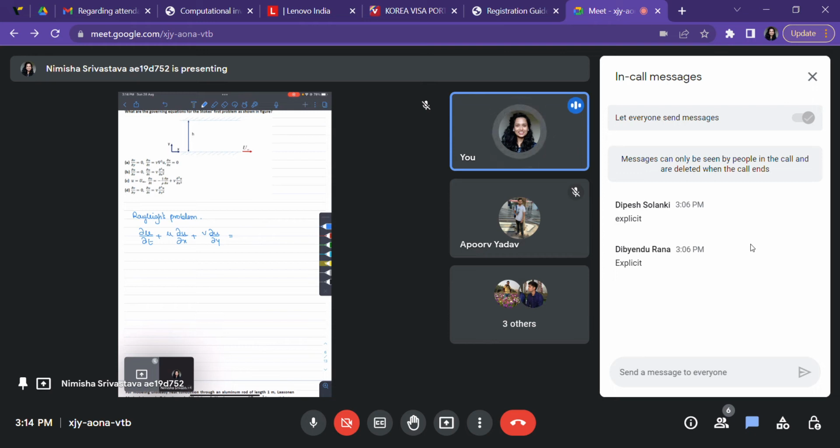The reason I said significant z direction rather than no z direction is that we just assume there is no variation along z. Realistically, we cannot just say that a problem is 2D in reality. It's only functionally 2D, because there is no meaningful variation or flow observed in the z direction. Then minus 1 by rho dou p by dou x. So this is my general governing equation.